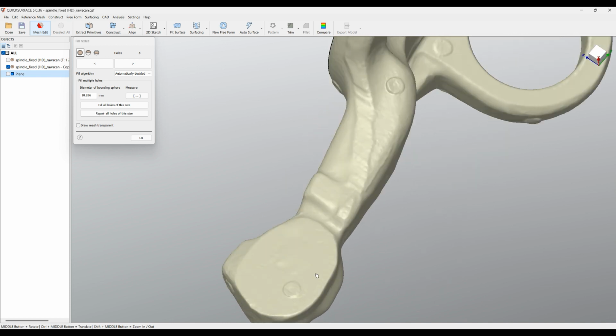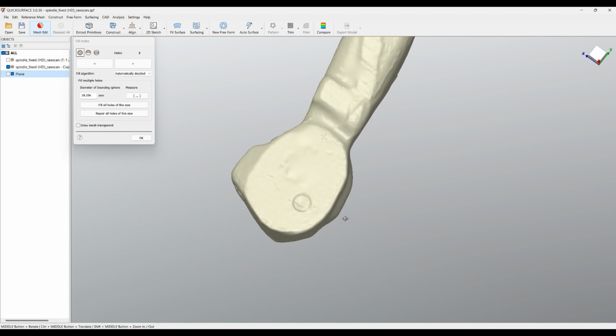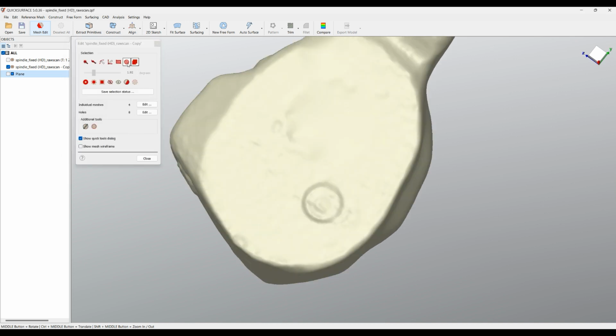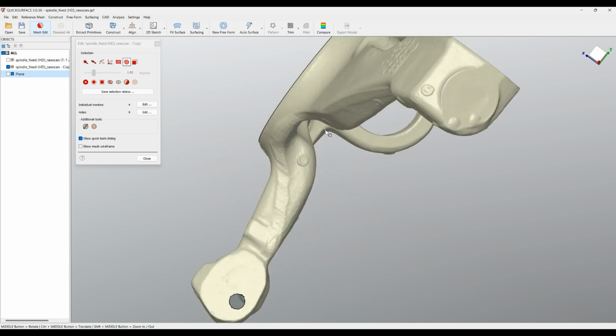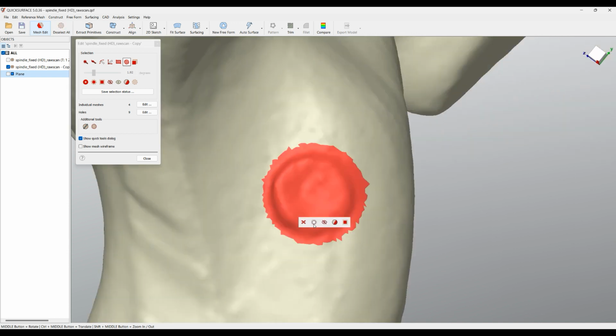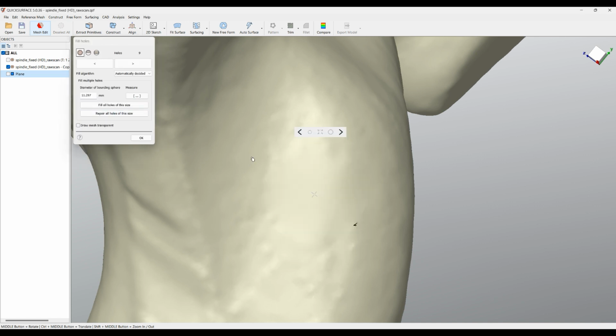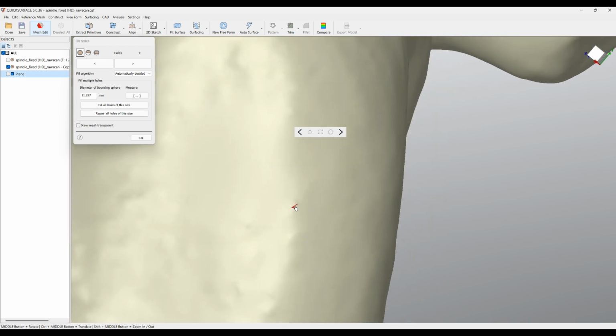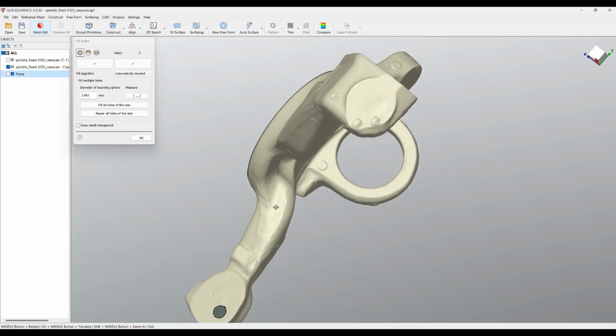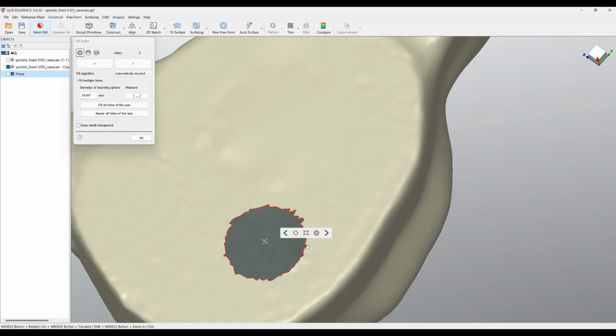Again, if you look at the object, these are markers. So what you can do to get a much better result is that you need to defeature some of them. In this case, I don't need to have this select through. I can just select this one, delete, go probably pick this one and delete. Go into the holes and fill them. Sometimes you may get some issues like this one. What you can do is just measure this size roughly, it's around 2 square millimeters, and then you can just repair all of this size. The software will automatically remove them. I can continue and close my holes.